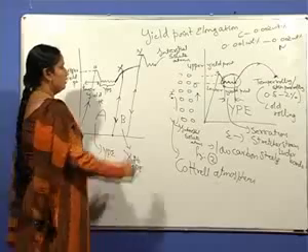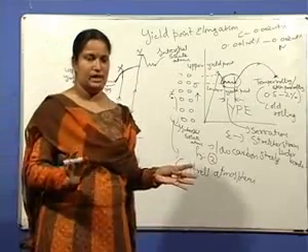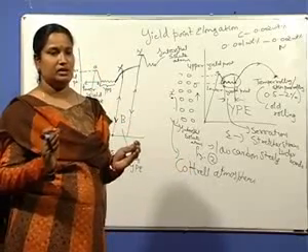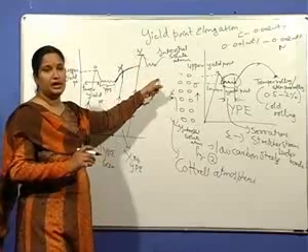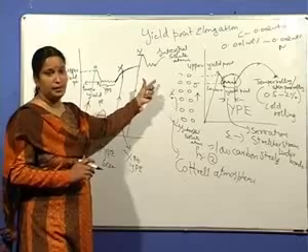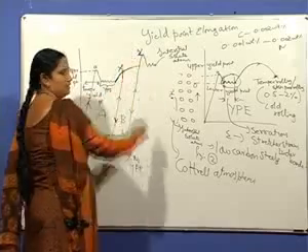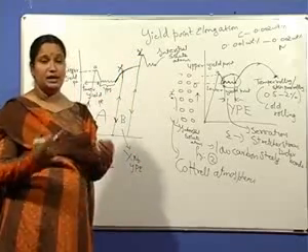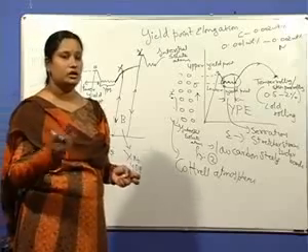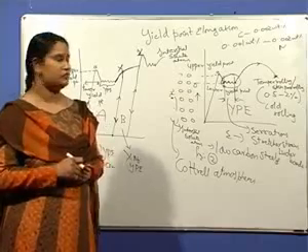Again unload that material. You leave it for several days at room temperature. Because of this room temperature aging, the yield point elongation is again seen. It reappears but at slightly higher stress than before, that is point Y. That is because sufficient time is given for the solute atoms, carbon and nitrogen, to diffuse again into the dislocation core and form atmospheres.